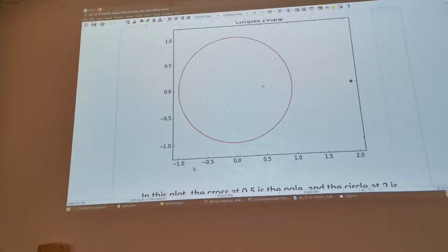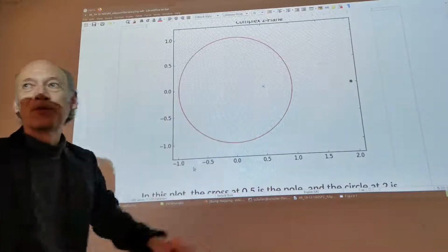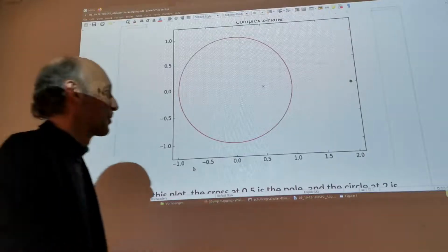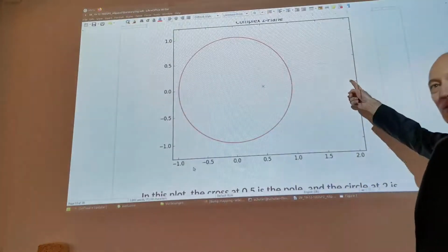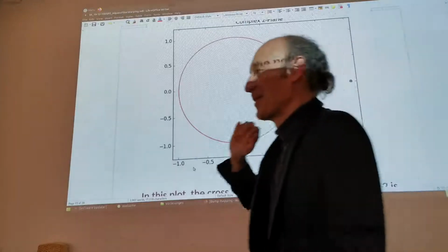Right, so if you have H of omega times 1 over H of omega, it cancels it. So this would be kind of like an equalizing filter. So what about the corresponding equalizing filter to this filter? Would that be stable? Why not? Because the pole will be the 0. Yes, right. Because then the 0 would become a pole and that would not be stable.